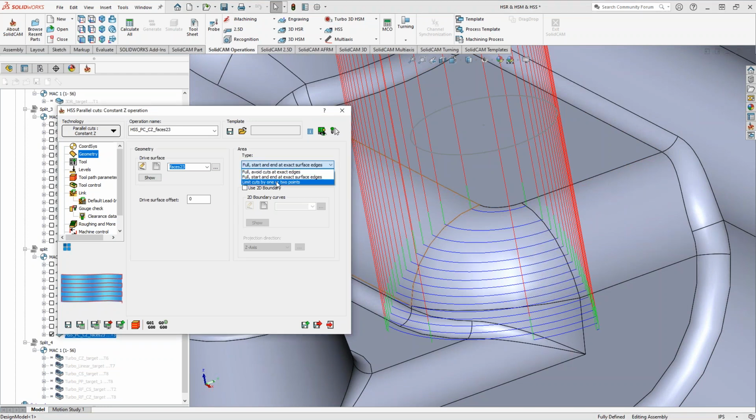Now, let's go to limit cuts by 1 or 2 points. I find this one very useful when you've chosen your technology, you've chosen your contours, whatever you're doing to define the toolpath, but it's just wandering a little too far in one direction or another. And the toolpath itself looks really good, except for maybe the surface is doing something crazy on the bottom there. This could be with the translated part. This could be with maybe just the technology that you've chosen. It works really well in terms of step over at a certain point.